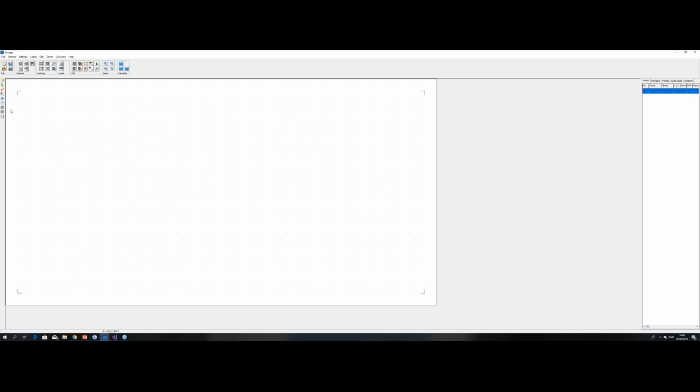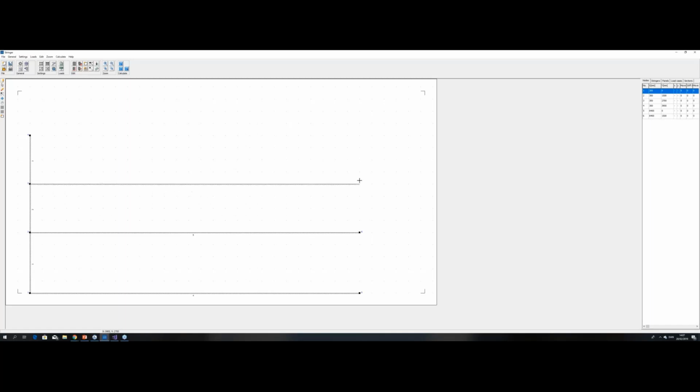We start to draw. A stringer model consists of some nodes and stringers. These are nodes and these are stringers. Stringers are mainly struts and ties, basically. They cannot take moments, only normal forces. We draw the model.